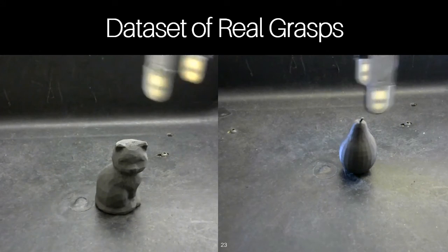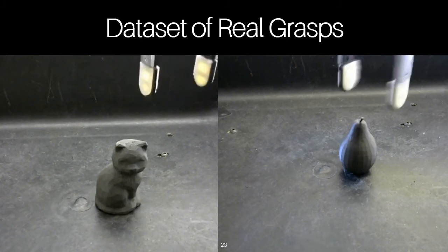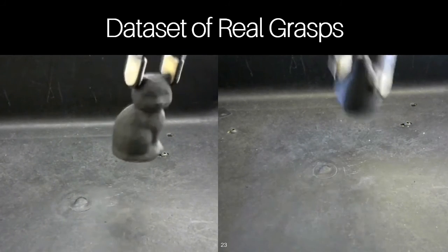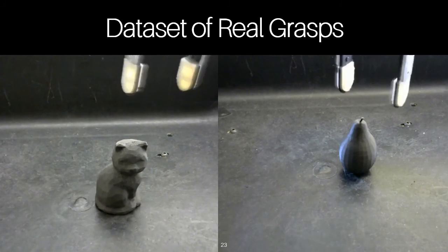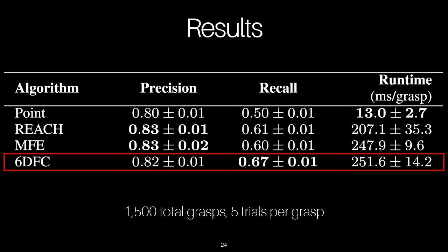We analyze our method of finding contact wrench constraints as compared to previous methods through comprehensive physical experiments. We collect a dataset of 1,500 grasps on 12 3D printed objects using a compliant parallel jaw gripper with an ABB Yumi robot. Each grasp is attempted 5 times to estimate its robustness. We measure precision, which is inversely related to the number of false positive predictions, and recall, which is inversely related to the number of false negatives, as well as the runtime of each method.